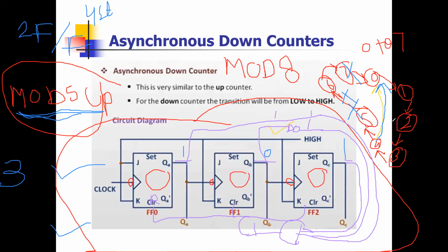And whenever they are getting 0, 0, 0, the counter will go to 1, then 2, then 3, then 4, and then it will go to 5. But it will not display 5, it will display 0. But always, before it reaches the AND gate, I have to make it 1, 1, 1.